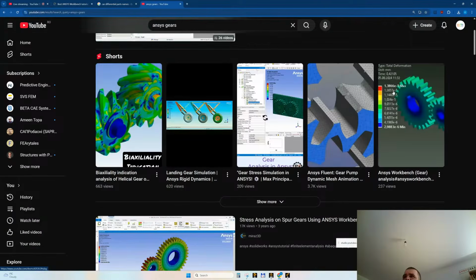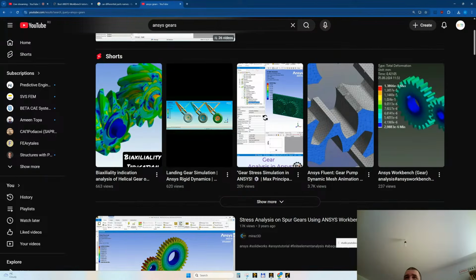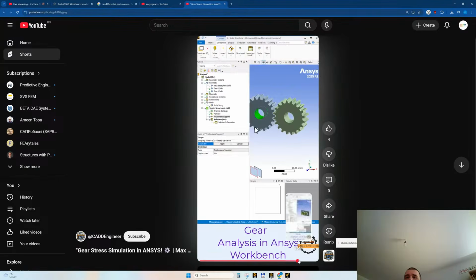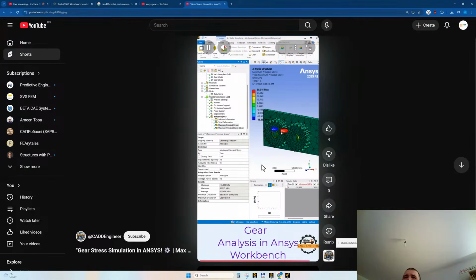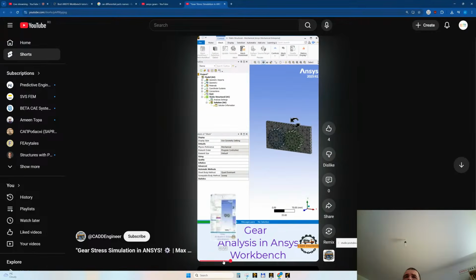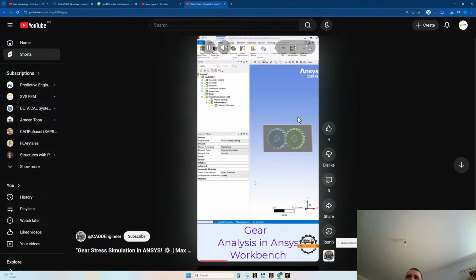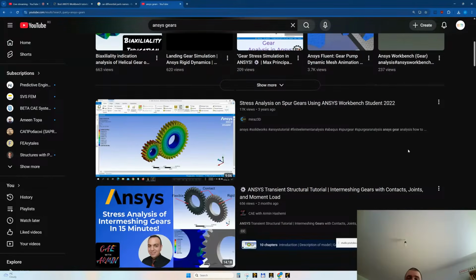All right, this is also ANSYS, also bonded contact, because why do you use bonded contacts in a lubricated assembly? Why? The friction coefficients should be almost zero. Yeah, it's also bonded contact here. What is the use? Please tell me, what is the use? No separation. Hey, come on. No separation because it does not converge with the frictionless or frictional contact. And that is where people get in trouble.